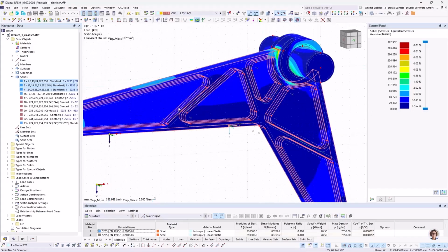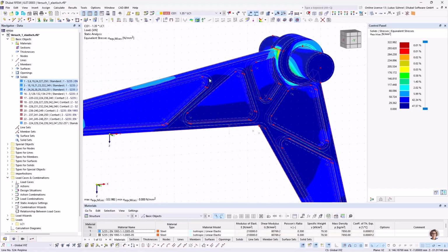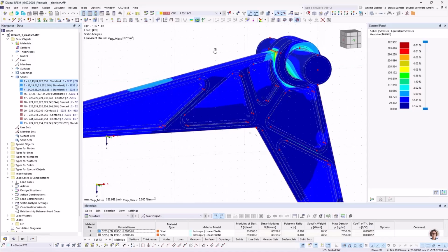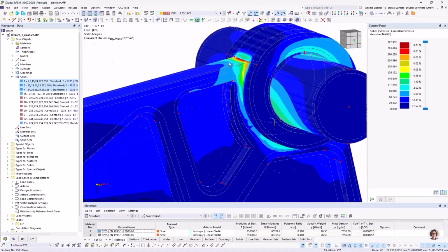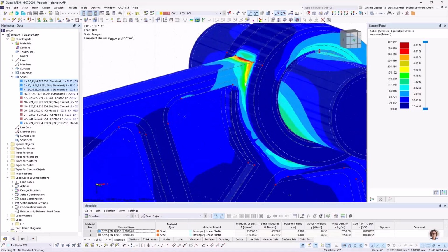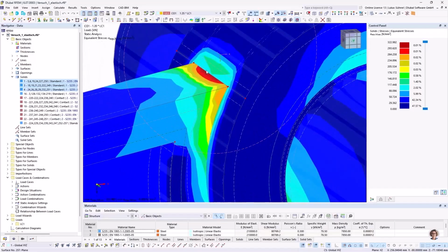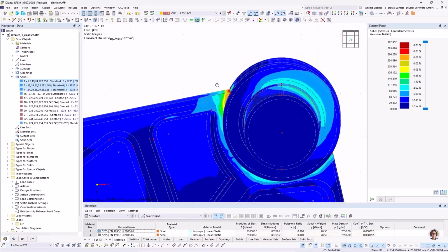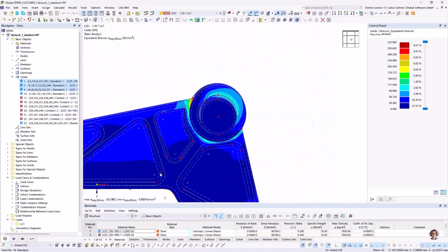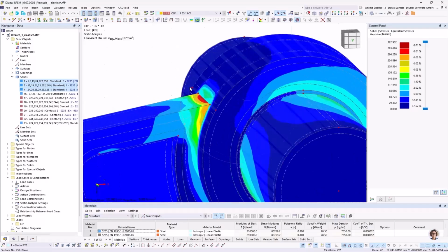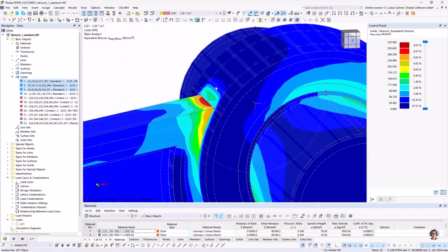So I guess we can definitely reduce more, or get rid of more material here to save weight, or alternatively, we could optimize the areas where we have stress peaks. And we can see we have a peak here in that area where we are connecting, let's say, this main beam to this axle support, to the circular solid.